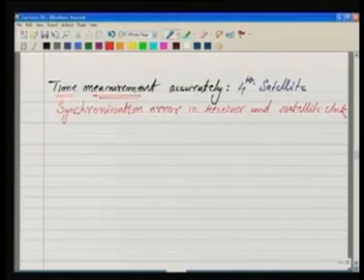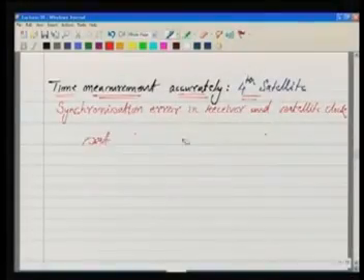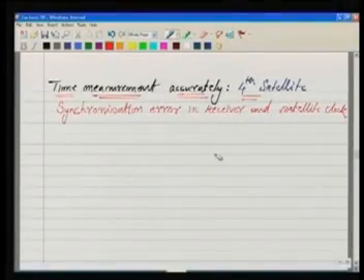Now one more important thing here. So far we were saying that we will need 3 satellites for positioning. That is okay theoretically, because one of the points can be eliminated, but in GPS we need 4 satellites for positioning. Now why 4? The answer is the clock which is being used in the GPS.